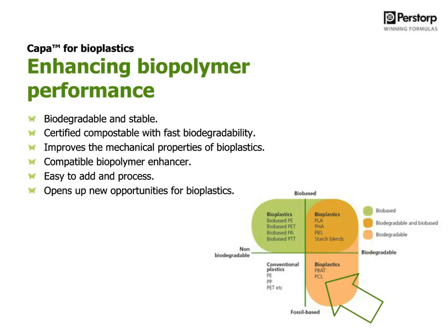Thanks to the properties of polycaprolactone, the low melting point, it has a nice and good dispersion, making it easy to add into your formulations and process them. It's not thermally sensitive, and it's not hygroscopic, which means that it's just a product you can add into your formulations and process it, compared to many other biopolymers which are moisture sensitive and thermally sensitive as well.